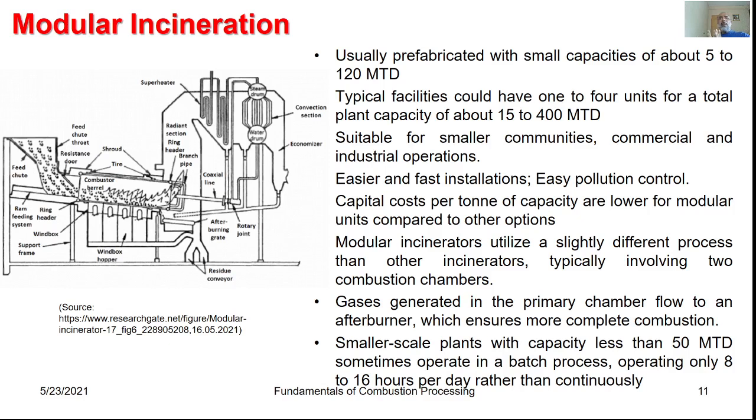They have capacity to incinerate waste of around 35 metric tons per hour, and even some facilities, like the one established in Singapore by Mitsubishi, have capacity to deal with 4,500 metric tons per day. So the mass fired systems or the RDF based systems are advantageous where a regional incinerator establishment is required.